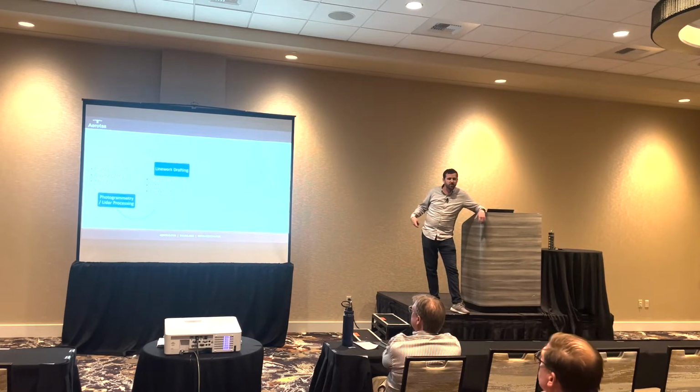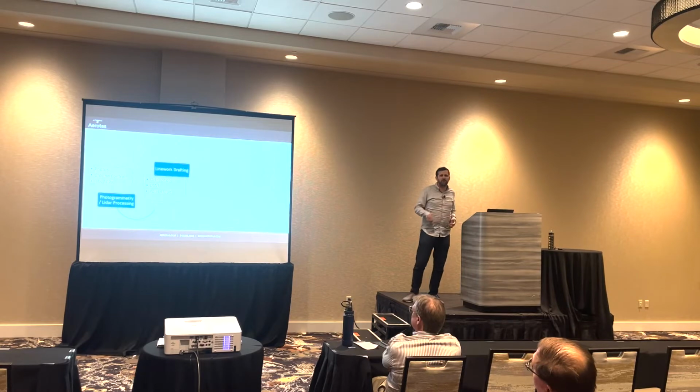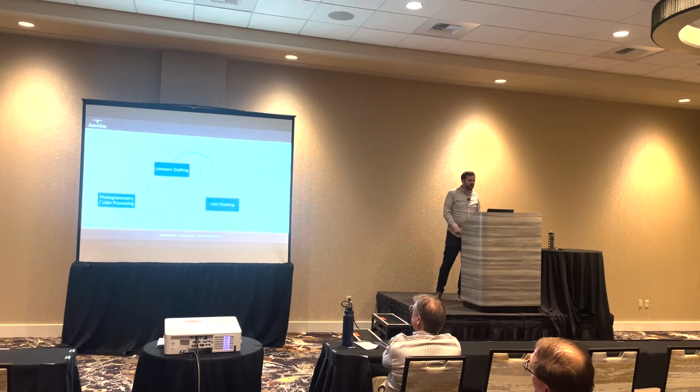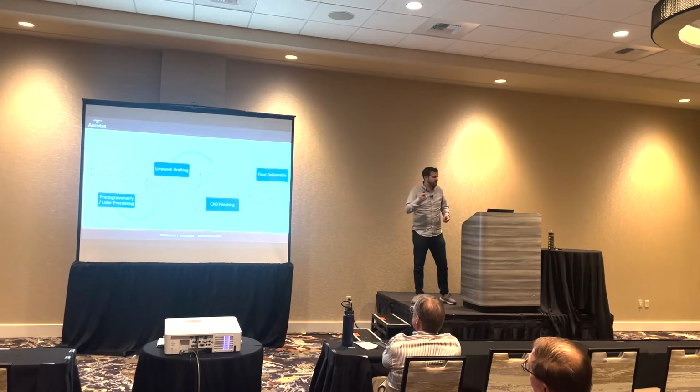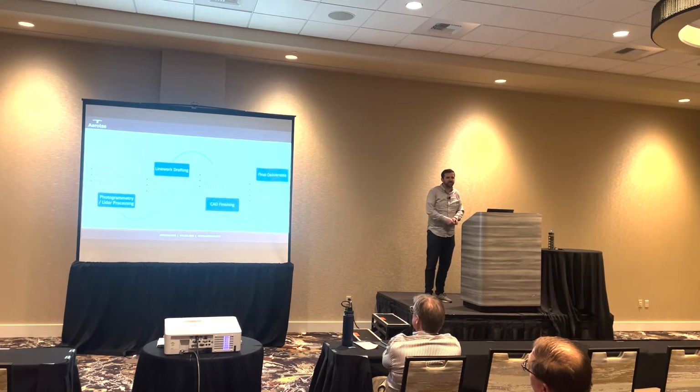Those are rich, cumbersome, big files that you can't deliver and send. Go through the line work drafting phase. That gets you your lightweight deliverables that are still lacking a little bit of context: points, polylines. Throw it all into CAD together. That's when you create your surface, your contours, and all of that stuff.